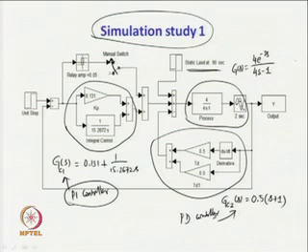So, it is very important to consider the effect of static loads for many systems, because the effects of static loads are there for many practical systems, and effort must be made to nullify the effect of the static load disturbance at the output during the auto tuning test.